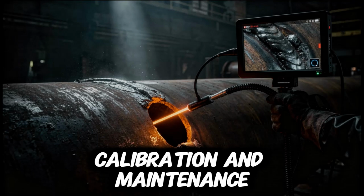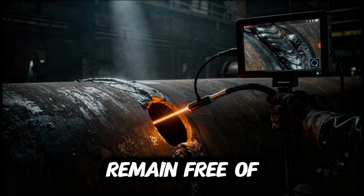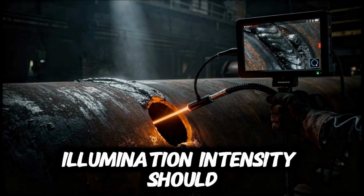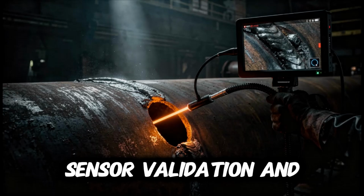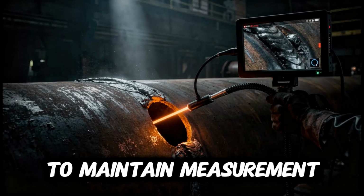Calibration and maintenance are non-negotiable. Optical surfaces must remain free of scratches and contamination. Illumination intensity should be verified periodically with calibrated lux meters. Digital systems require sensor validation and software version control to maintain measurement accuracy.